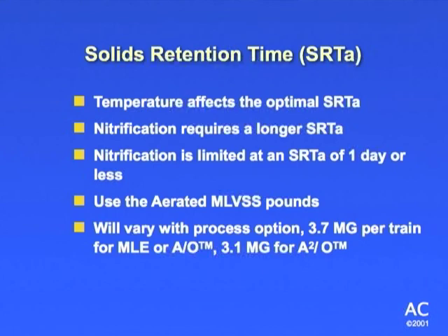So nitrification, basically we're trying to get across, nitrification requires a longer SRT, and it's limited at an SRT of 1 day or less. So you can have nitrification even with a 1 day SRT. Is it going to be significant? No, not enough to be worth your while. But it does happen. Okay, it's occurring. What you want to do is get it into the sweet zone where you're getting a lot of nitrification occurring. Okay, so that's why you want to have a longer SRT. And as we said previously, we're going to be using the aerated mixed liquor volatile suspended solids pounds for our calculation.